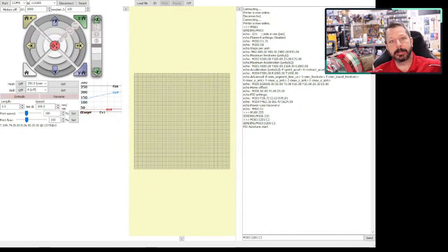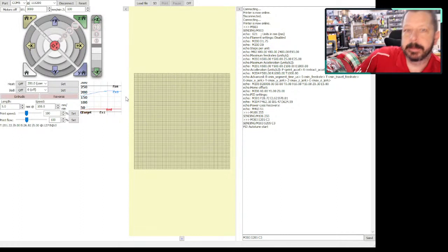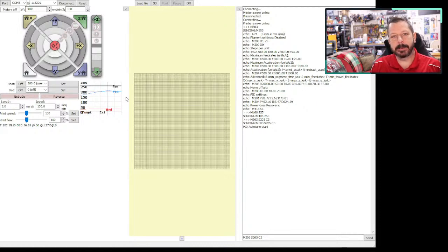If I integrate the existing, like you can look at our little graph here, I've got a curve, and I can calculate the area under that curve, and that's integrating it. So now I'm looking at the past, at what it's been doing, and by integrating the area under the curve of the heater as it heats up in the past, I have a snapshot of the things it's been doing over time, and I can use that past data to adjust for what I want to do next.